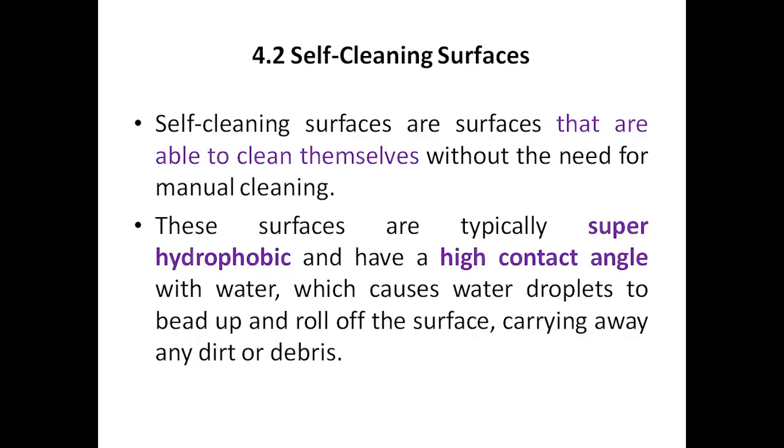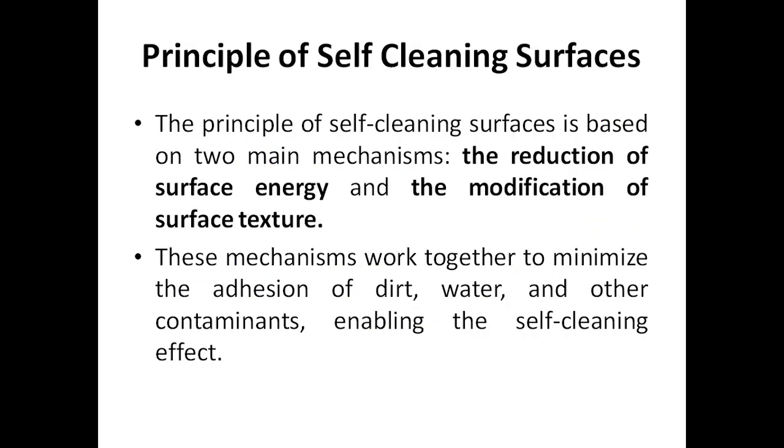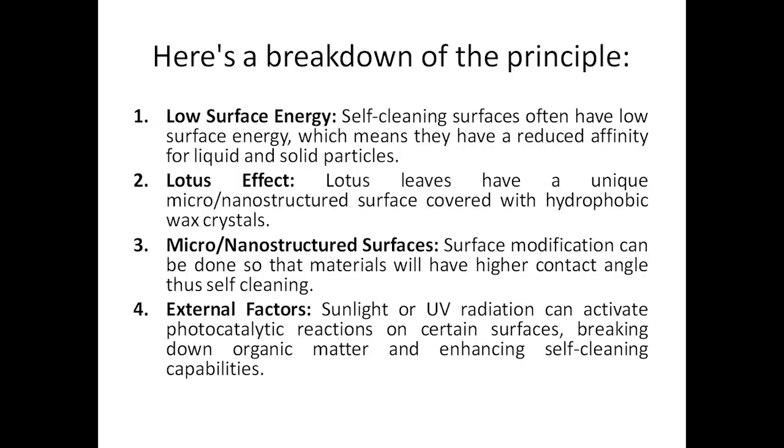Next, the self-cleaning property, as we discussed, where surfaces clean themselves, which is called the self-cleaning property. The super hydrophobic nature is there, high contact angle, again the same thing, and it will take the debris off. The principle is also the same: the reduction of surface energy and the modification of surface structure, because by doing so we can have hydrophobicity so that it can take off the dirt. Next, here is a breakdown of the principles.